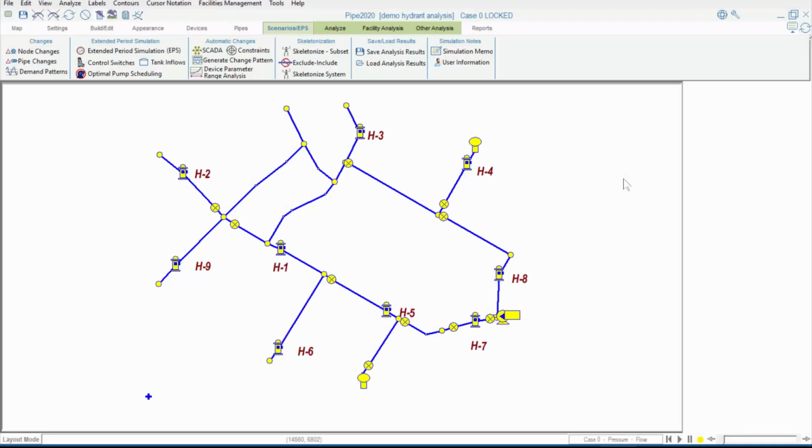We can also use hydrant data to model a connection to a larger system as opposed to modeling the entire larger system. Let's say we want to prove that this subdivision can meet a certain minimum pressure. We set up scenarios like that using a node called a pressure supply, which we model using field test data from a fire hydrant that's as close as we can get to the connecting pipe to the main system.